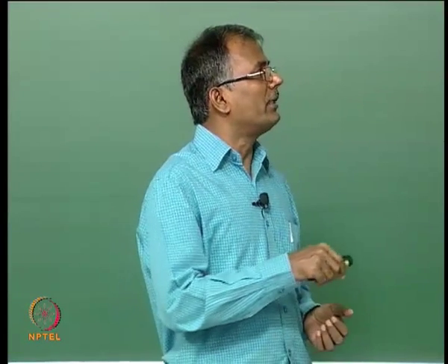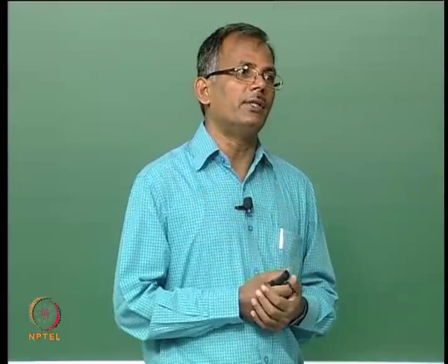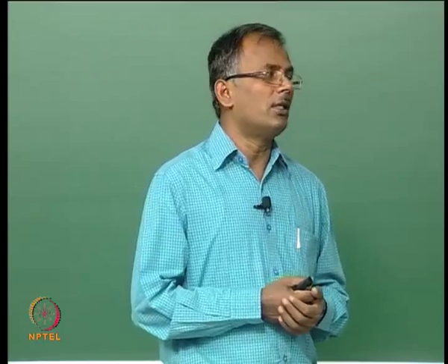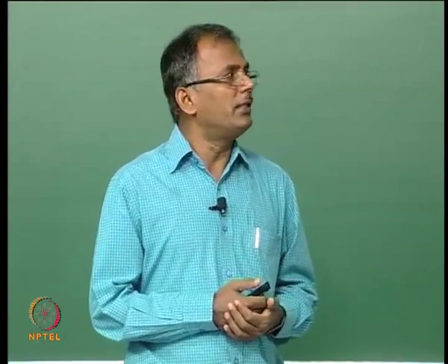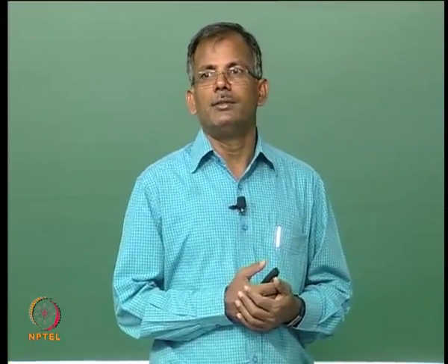But imagine if you take the same cylinder with no weight, you just put it in water, what will happen? It will float horizontally, isn't it? So, we are just trying to manipulate this buoyancy and the weight so that it comes into this position. Once it comes into this position, then a sufficient number of moorings to station keep is a simple system.